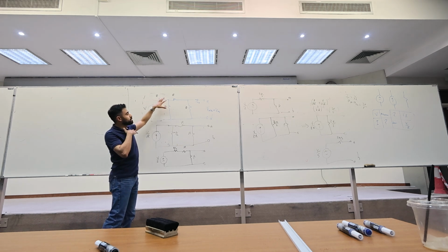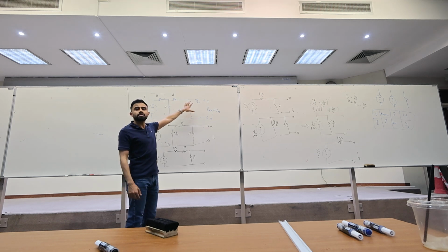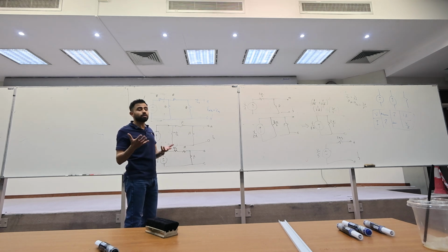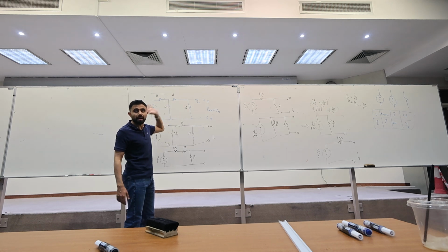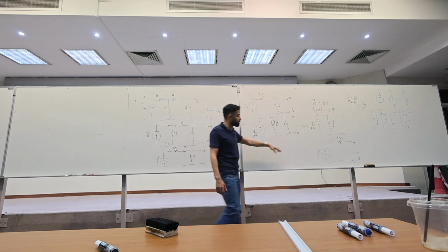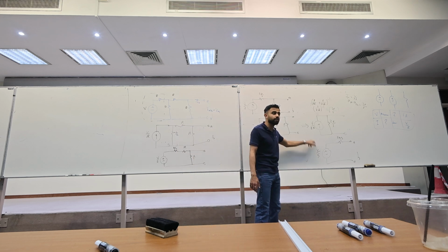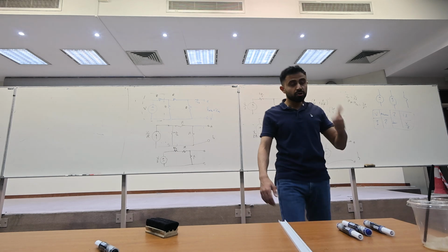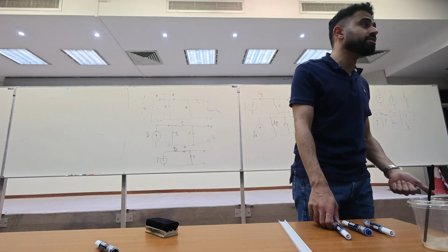This problem asks you to find the Thevenin equivalent, the Norton equivalent, and R Thevenin. We said R Thevenin is the same. What makes this problem tough is everything is R, and students, when they don't see numbers, they panic. In the multiple choice questions, Dr. Atiyah will put V over 5, V over 6, V over 7, V over 8. So you have to solve it using source transformation.